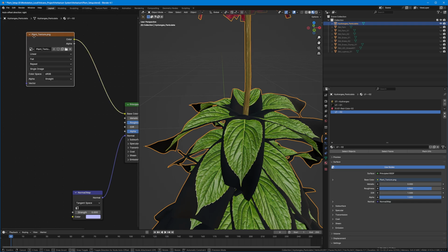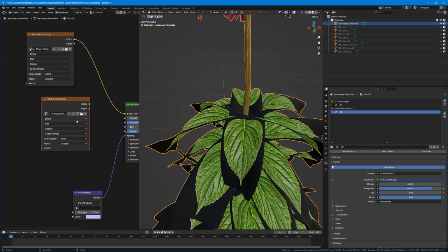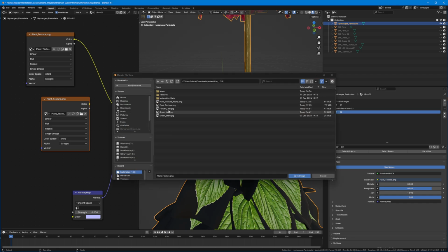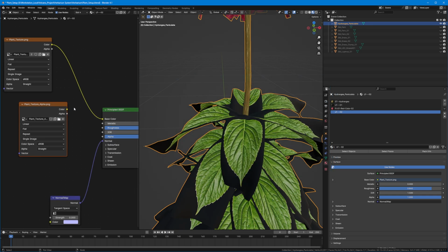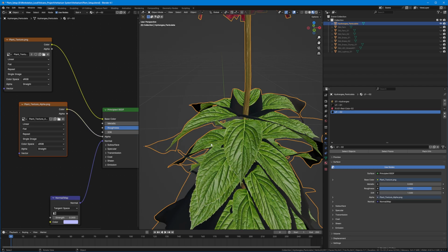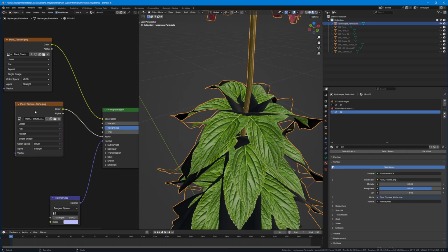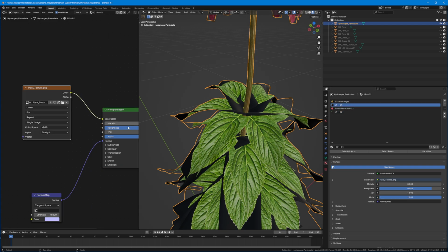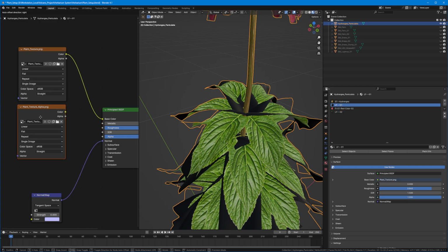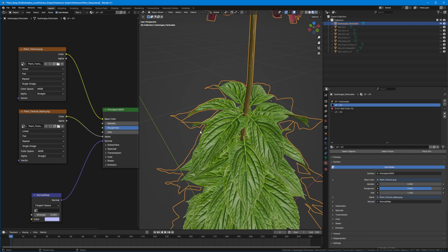So let's get started. We're going to go back into Blender over here, and we do need to bring that map. So I'm going to Control-C, Control-V this, because I can now just click on the Open button and select the alpha. And I can plug this over into the alpha like that, and that should now give us what we need. We do need the same map bringing over into here as well. Okay, and copy it and again into the alpha.